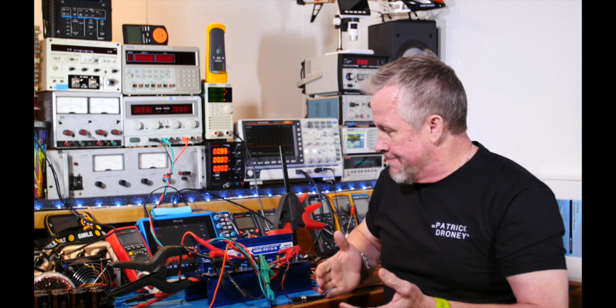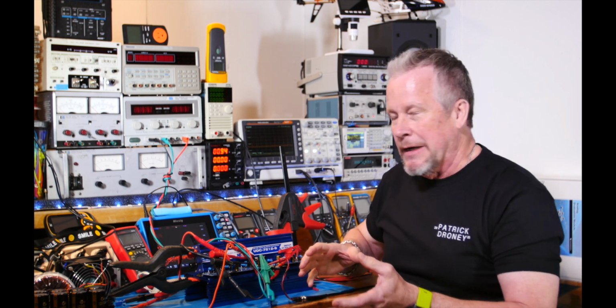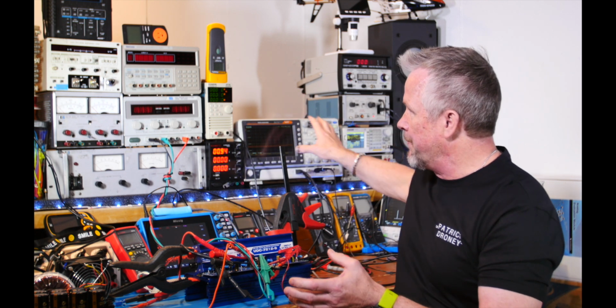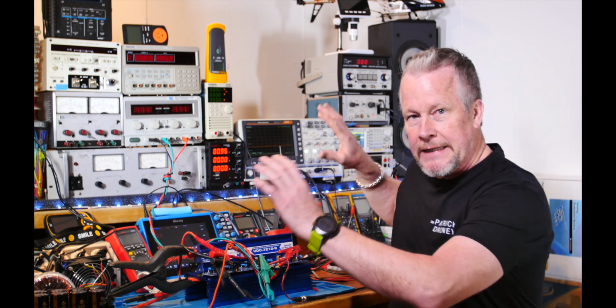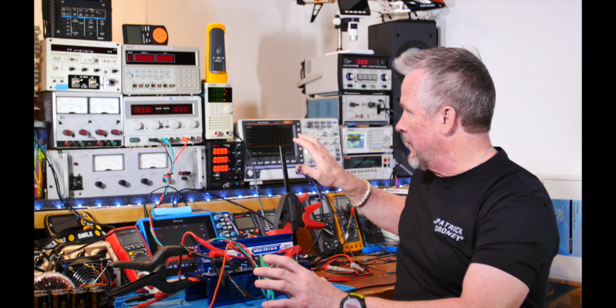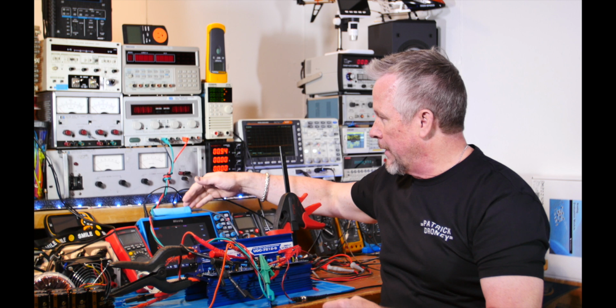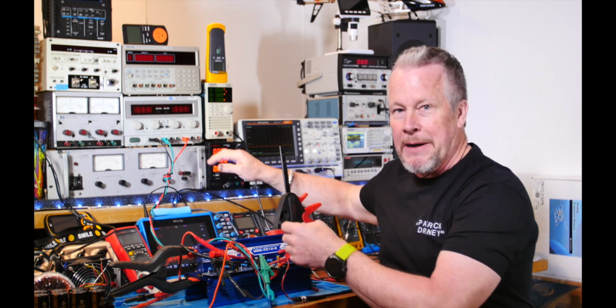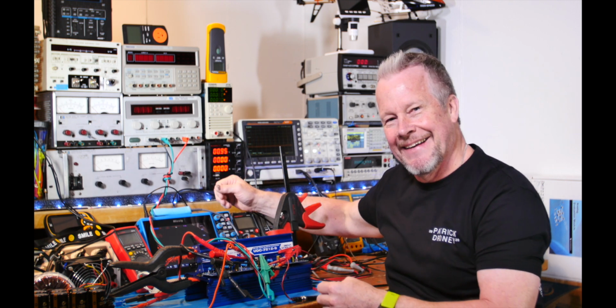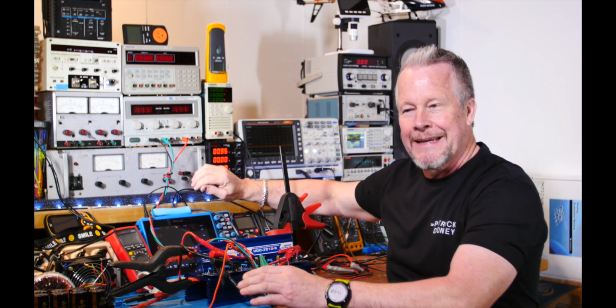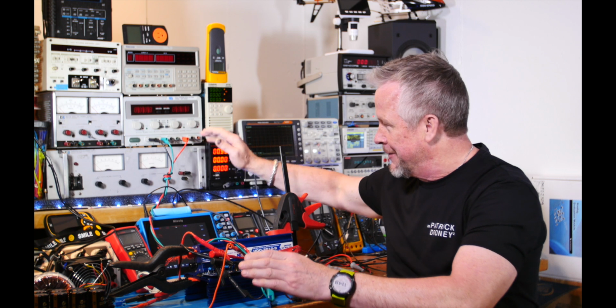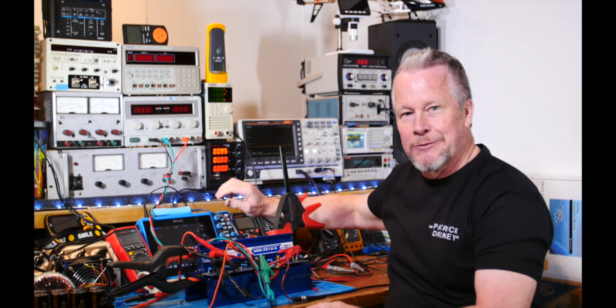And just in regards to chassis, anything metal, agencies will say you have to have that tied to chassis ground, so everything is referenced at the same level. So I don't touch a floating scope and then touch my power supply and go, ow. They say don't let some human equalize the voltage potential. Make sure they're all tied to the same chassis ground.